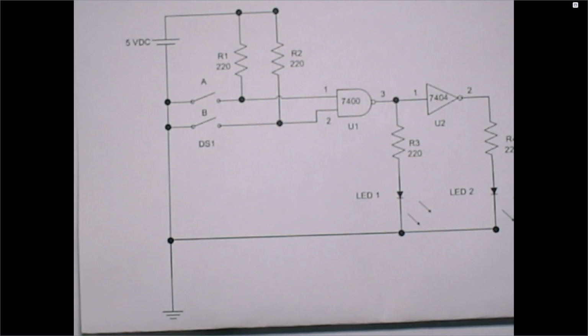But again, the LEDs are used here to see what the logic is. For example, if you want to check a logic at one point, we plug in an LED. And just by the LED, we see whether it is turned on, which means the logic is high. If it is turned off, it's 0. We just want to see how the LEDs are working, and based on that we see whether the logic is 0 or 1.